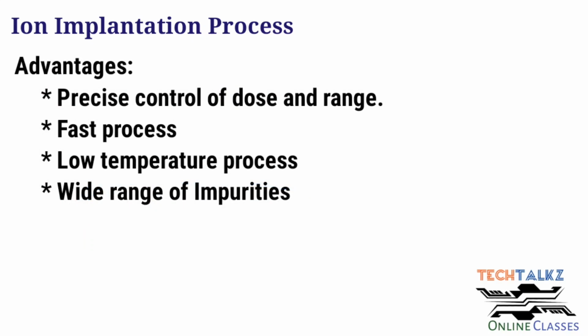So these are the advantages of the ion implantation process. The precise control of dose and depth. It is a very fast process. Then it is a low temperature process when you compare it with other diffusion processes. It also permits a wide range of impurities.